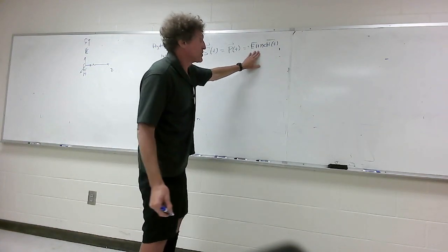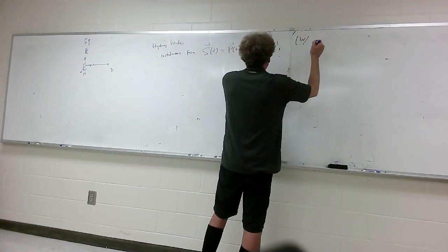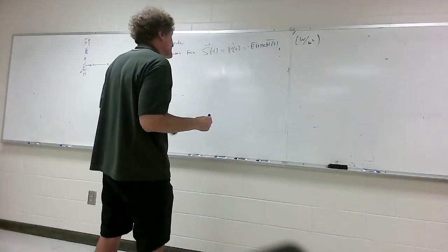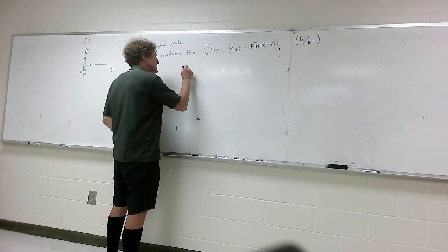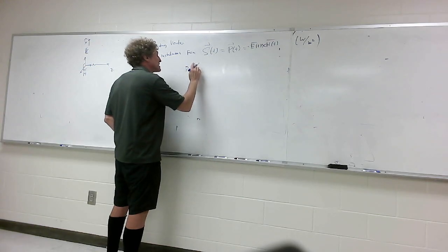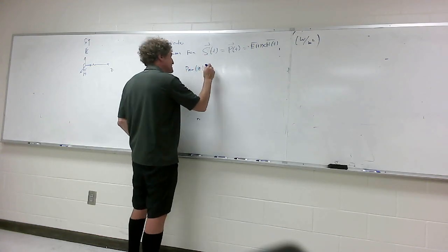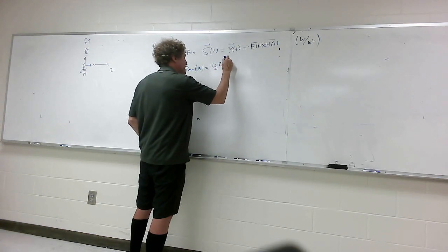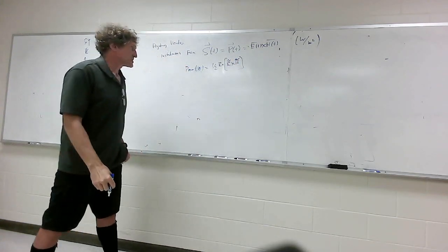The units would be watts per, and if you think about this, volts per meter times amps per meter, watts per meter squared. And it is the power flowing through a certain area. But what we really care about is the average power density, and really P-av, and it's a function of Z, by the way. And that's given, and he has it there as 1/2 the real part of E crossed into H conjugate. I'm going to do this for you. I showed the answer to this one already, but I'm going to do it.